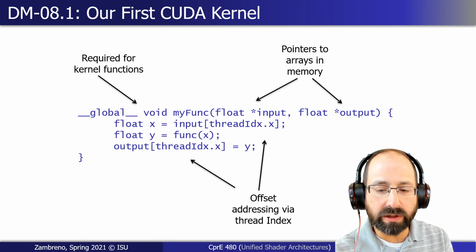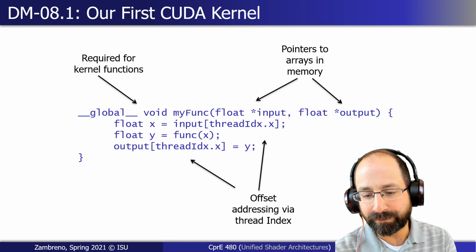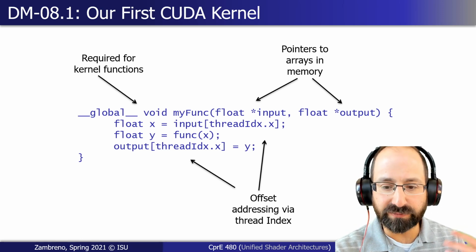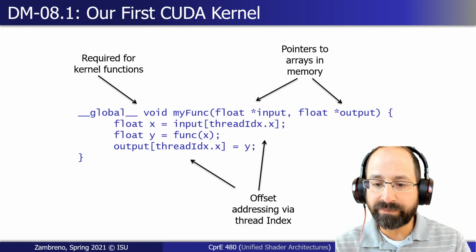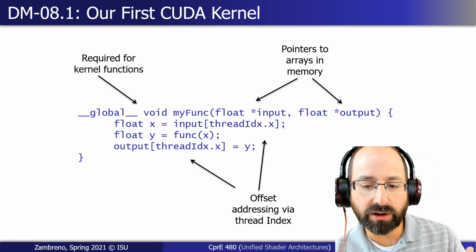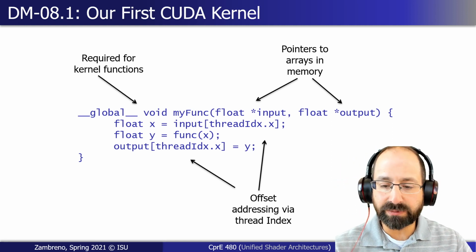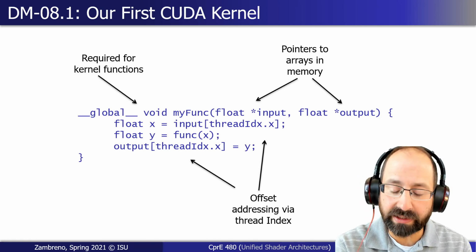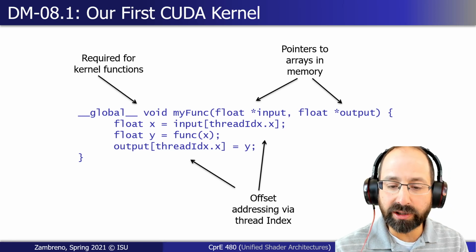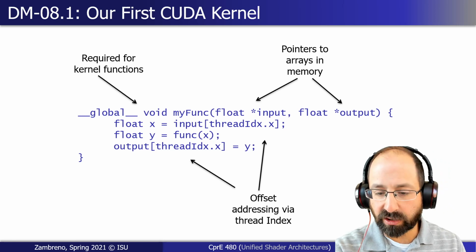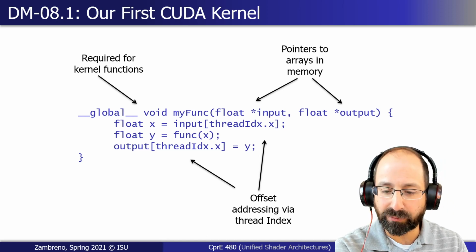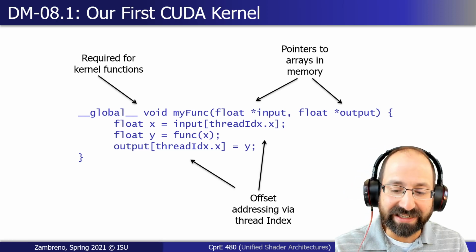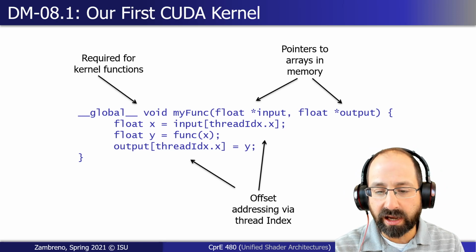The same kind of things we are interested in doing for vertex and fragment shading and all the other shaders we have, we want really efficient memory lookups. We want to be able to do matrix vector multiplication as efficiently as possible. We want some ability to accelerate all those trigonometric and other special functions. That same exact functionality that we need for graphics rendering. Well, the math is very similar. It's not necessarily exactly the same, but there tends to be a pretty good correlation between what the graphics hardware is already going to need to provide better and higher performance graphics and what we can then get for higher performance general purpose computation. So it's not an accident that it evolved in that way.